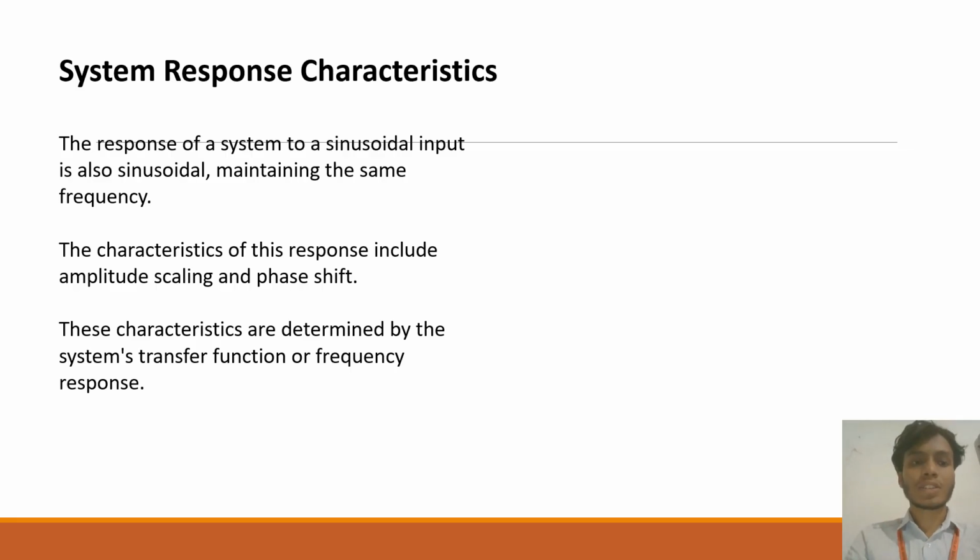System response characteristics. The response of a system to a sinusoidal input is also sinusoidal, maintaining the same frequency. The characteristics of the response include amplitude scaling and the phase shift. These characteristics are determined by the system's transfer function or frequency response.